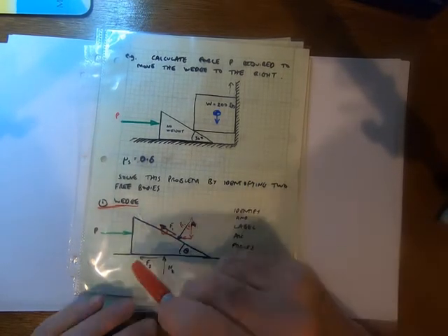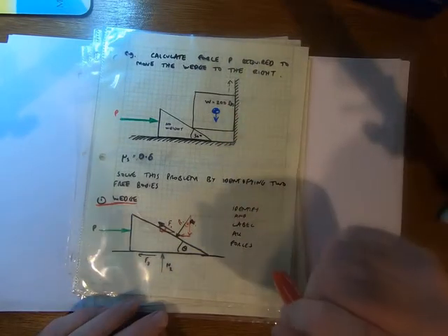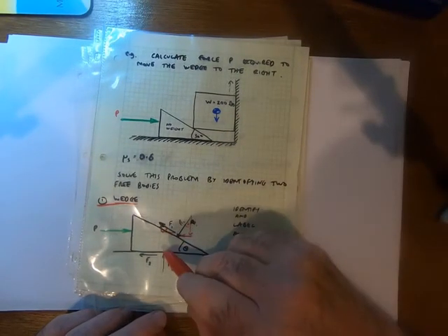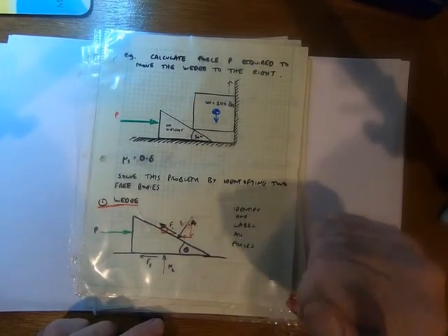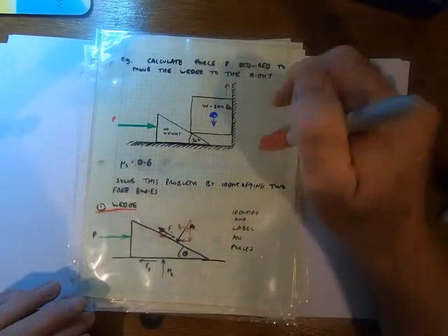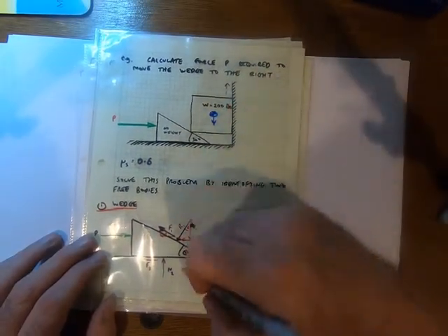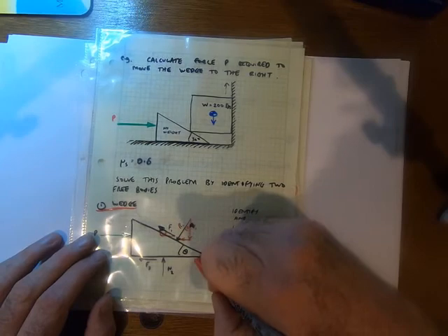You don't have to start with the wedge. You can start with the block. There's a number of ways of doing this. Big sketches, and then work methodically. I wouldn't put numbers in early. Stick with variables while you do the algebra.